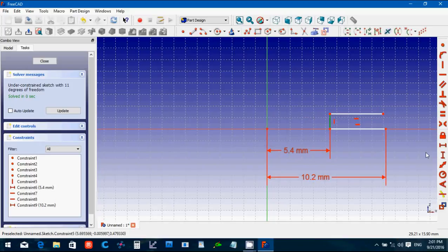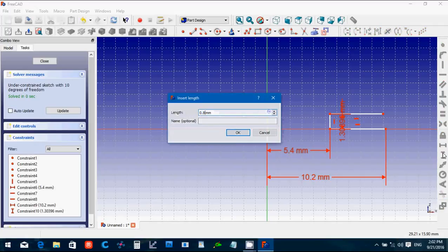Now this height, the thickness of this metal, is like 0.4. If I'm going to try to 3D print this, I might want to go thicker than that. So I'm thinking 1 millimeter is probably a good thickness. How about 0.8? I'll make it 0.8.